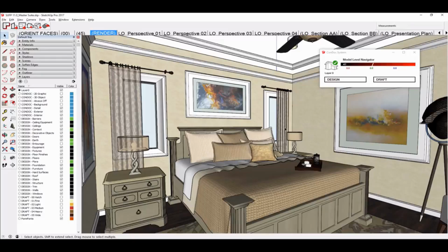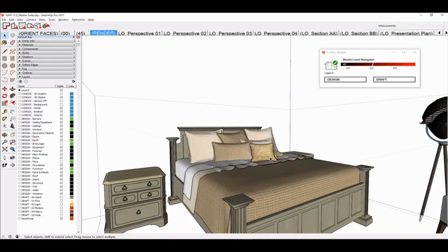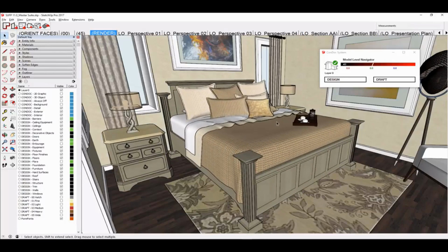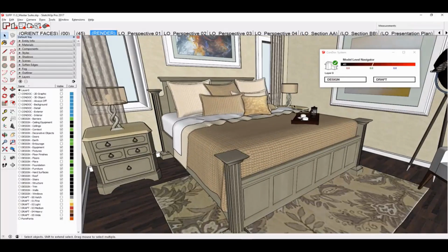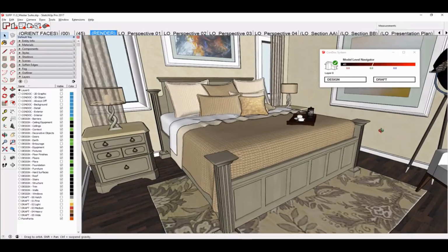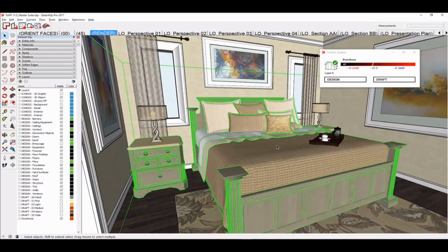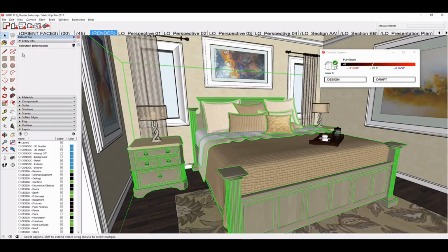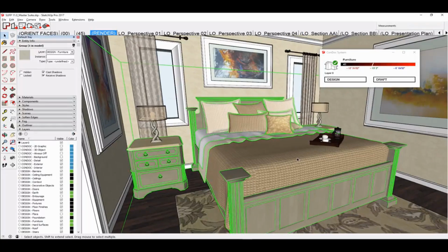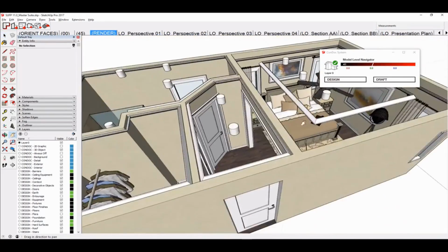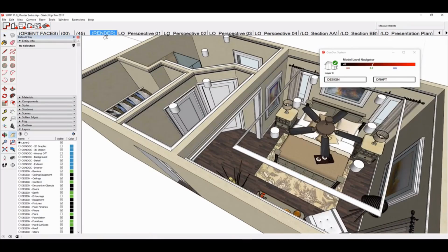So if you check this out, you can see that we've got our furniture. I can double click in and isolate my furniture. The way this system is set up is you create a group, assign one of these design layers to the group, and put the objects in that correct group. So in my furniture group, this is on the layer design furniture, I add my furniture. On my walls, add my walls. And what happens is we have this nice clean SketchUp model that's ready for import.